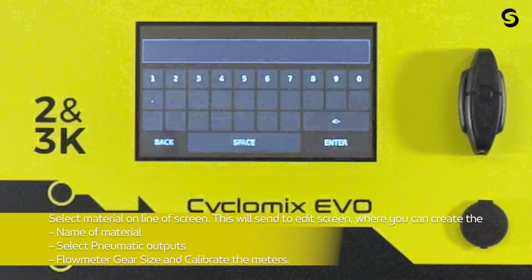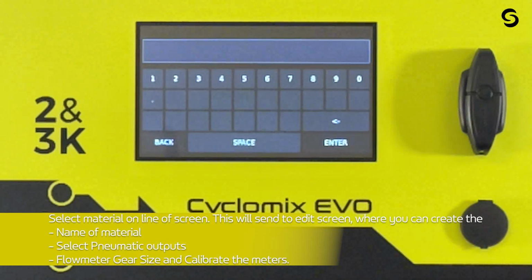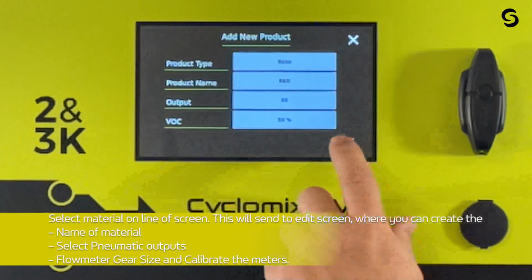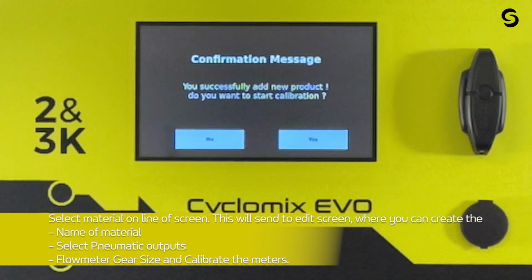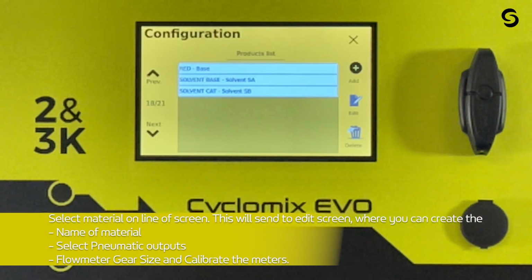Again, I can set my VOCs, and that's going to come from your product data sheets from the paint supplier, and I'll say it's 50% solids or 50% solvent, and then hit my check mark. You've successfully added a new product. Do you want to start the calibration? This particular time I'm not going to start, so I'll say no. And it was preset in there 0.24. So that's going to be pretty close and should be able to get you started, but you should always calibrate at the beginning of the process.